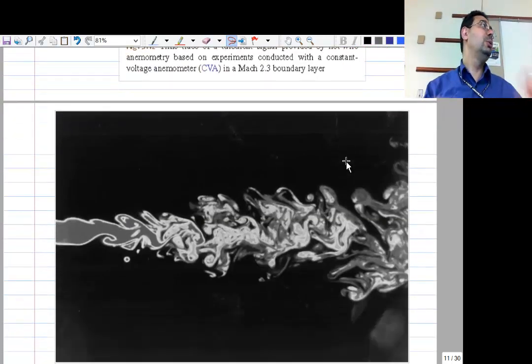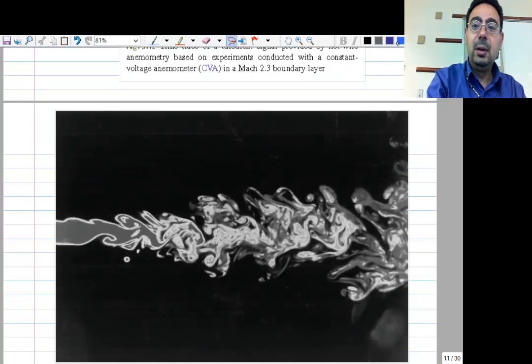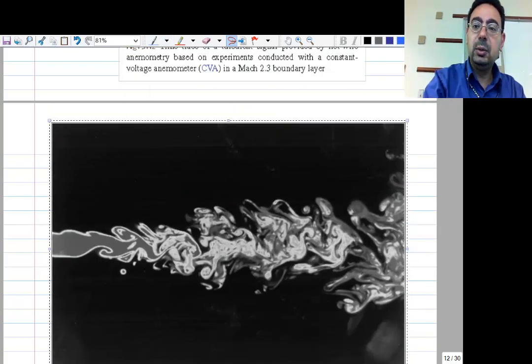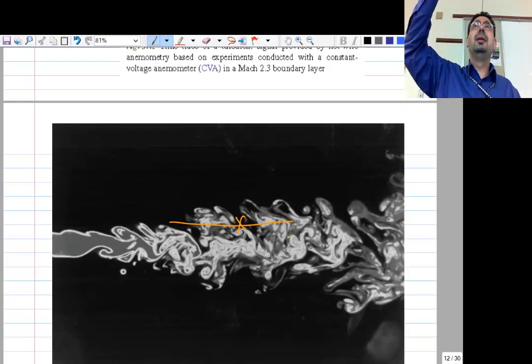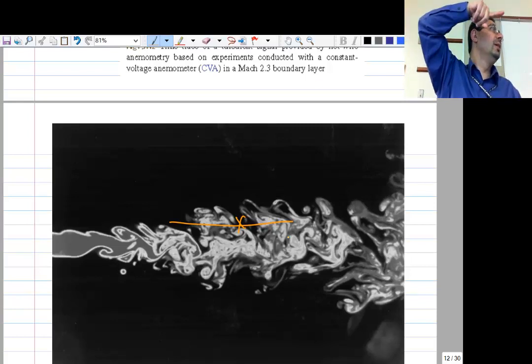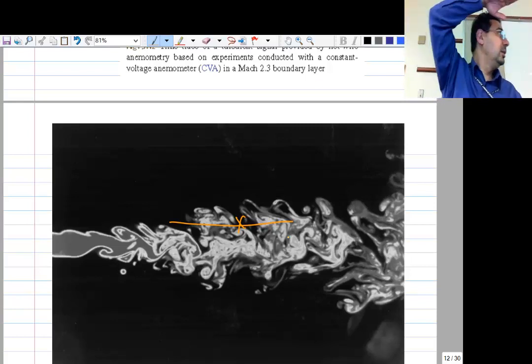And so with the advancement of laser diagnostics and imaging, they figured out there is actually large-scale structure. There are all those rolling vortices, and if you have your wire or the device that you are measuring with sitting over here, and those guys are passing by, you will come to a place where you don't measure anything. And then one of those guys will roll over and you'll start measuring, tack, tack, tack, tack, tack. And then silent, and then coming again.